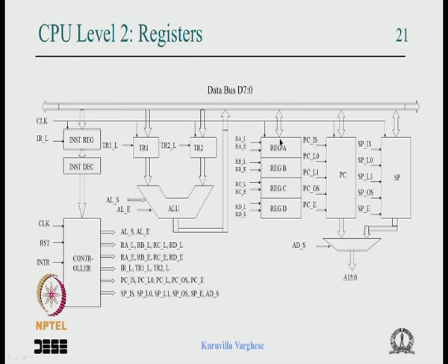And we mentioned that this latch signal is not going as a clock, because it is possible that we want to continuously load the data in some application, maybe not with the CPU register. In that case it is very convenient to keep this latch signal or enable signal high for, say, 10 clock cycles.